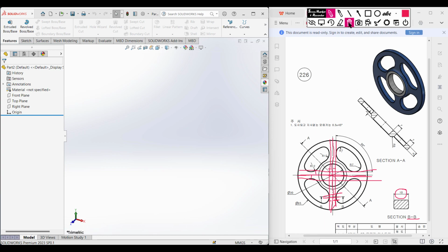So after doing all of that, I will trim all the extra portion. Then I will use the fillet here, and here we can see fillet of 7 radius, and there we can see we have another fillet here and here, and this fillet has a dimension of radius 12 unit. Okay, so let's go back to our SolidWorks.